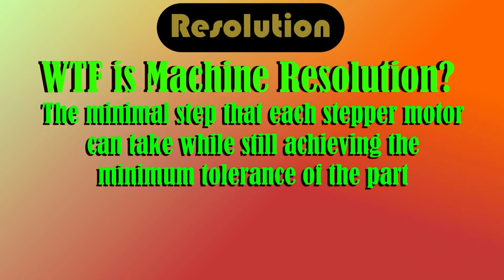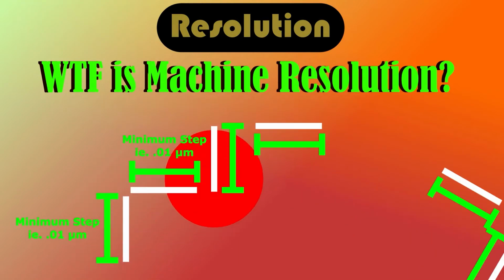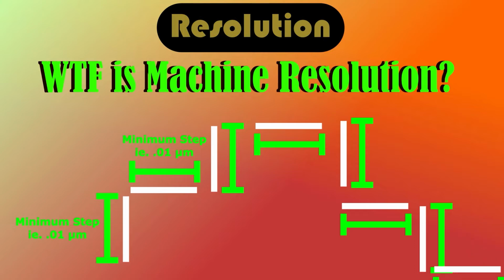And now, I'm sure you're wondering, what is machine resolution? Well, machines are typically controlled by a stepper motor and stepper controller, which can only move smoothly at specific feeds as they have a minimum step over. Angular and circular motions are made by moving two or more motors in a micro-stepping motion, creating little L-shaped patterns that are relatively unnoticeable at the proper resolution. If you're seeing stepping in your finished part along the line of motion, you've exceeded the maximum machine resolution.